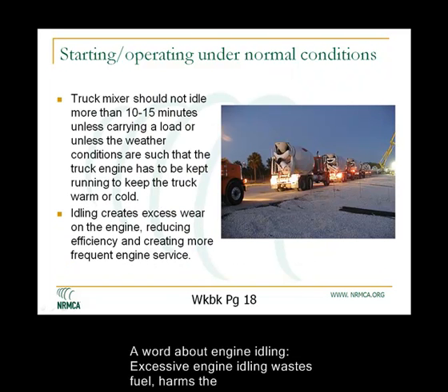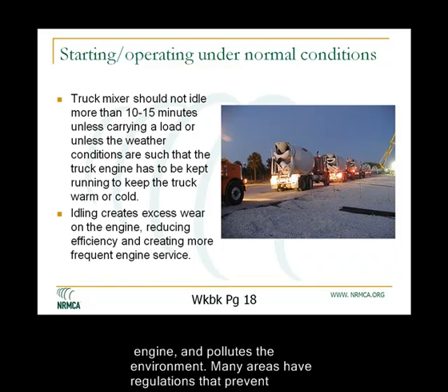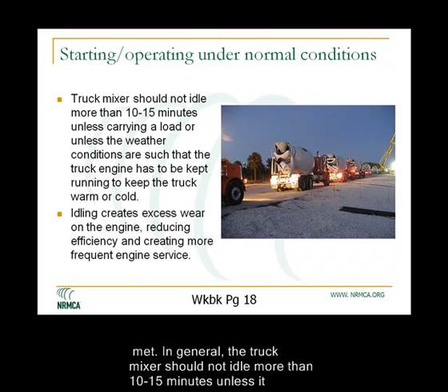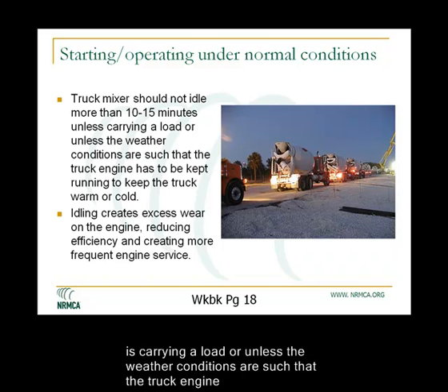A word about engine idling. Excessive engine idling wastes fuel, harms the engine, and pollutes the environment. Many areas have regulations that prevent trucks from idling more than a specific period of time, unless special conditions are met. In general, the truck mixer should not idle more than 10 to 15 minutes, unless it is carrying a